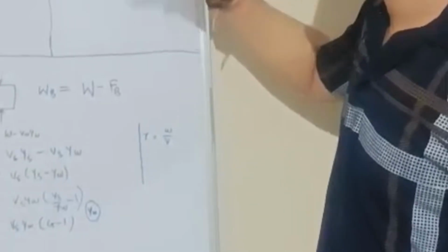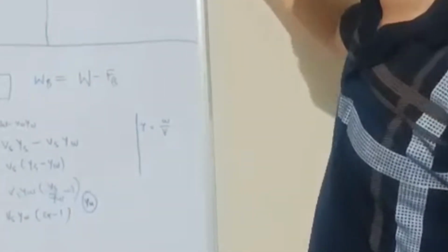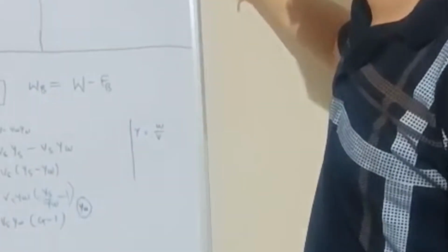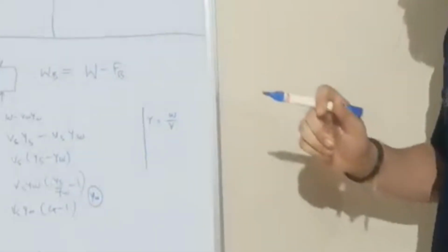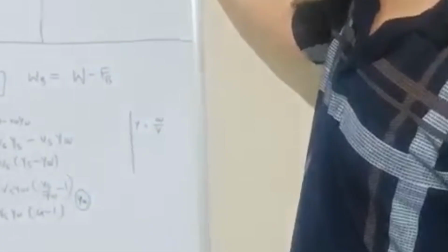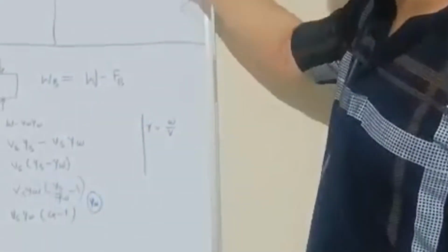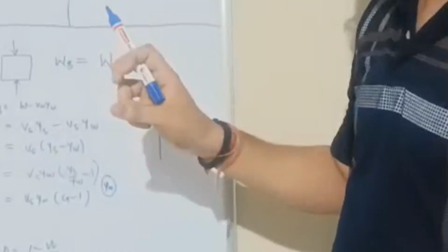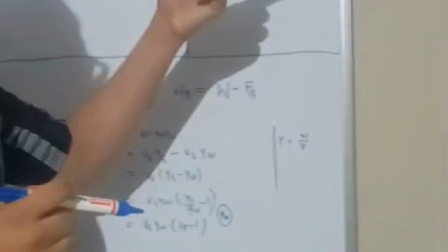So this sand offers the resistance. To counteract this, we have to provide the extra head so that the filtered capacity is increased. When we provide the extra head over the pre-selected head, water can speedily go through the filter media.